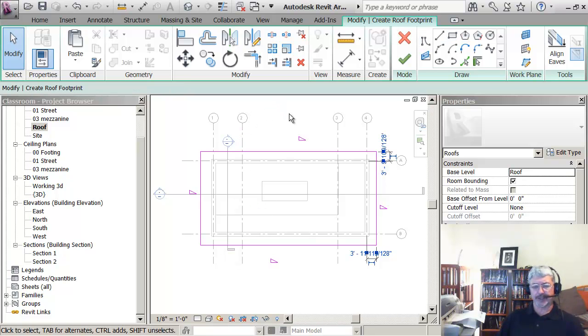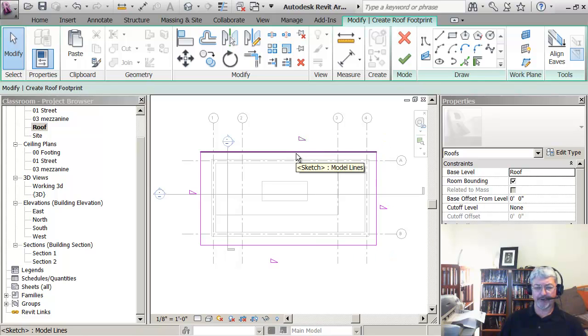If you look at the sketch, the triangle indicates that there's a slope coming from that line. That line, if you like, would be a wall plate or something like that, and then the rafters are coming back towards the ridge line, and that indicates that there's a slope.